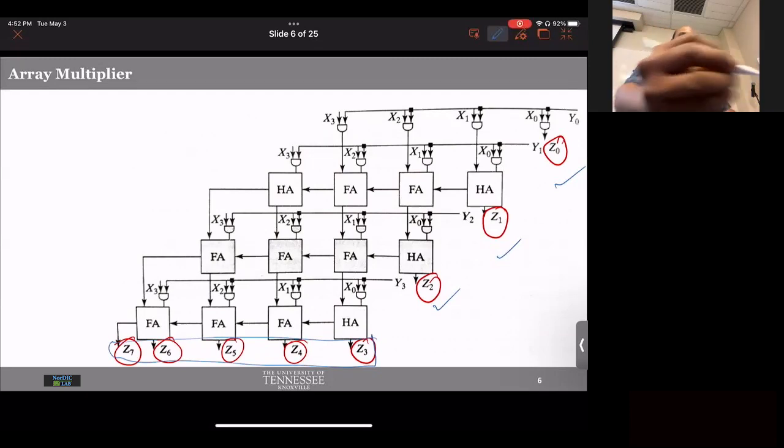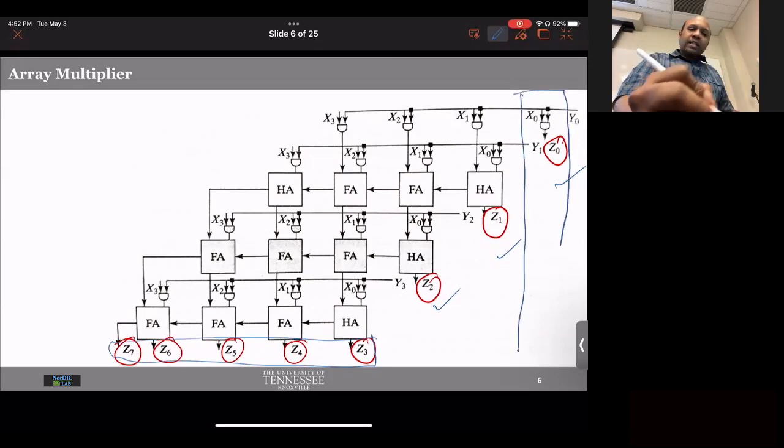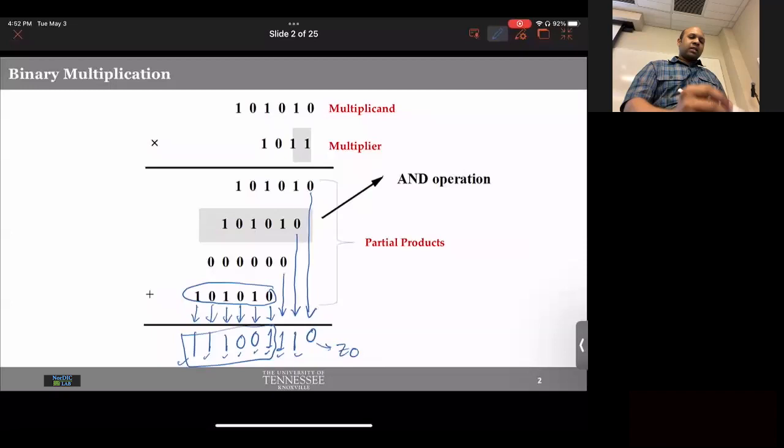Okay, so I've done the easiest part. The first output should directly go to Z0 without any adder. There are no adders here at all. There is something interesting about the second output as well. Let's mark it out. The second stage, you need to just add 2 bits, not 3. Is there any carry in from the previous stage? Why not? Because we didn't even add anything. There will not be any carry. So this guy has 2 inputs, no carry at all.